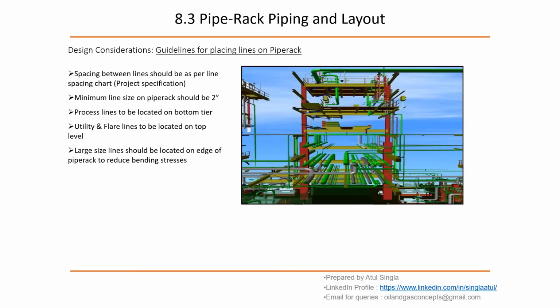Utility and flare lines to be located at the top. The flare line is the largest size, which is always at the top section. All the utility lines are below that. These are all the utility lines.